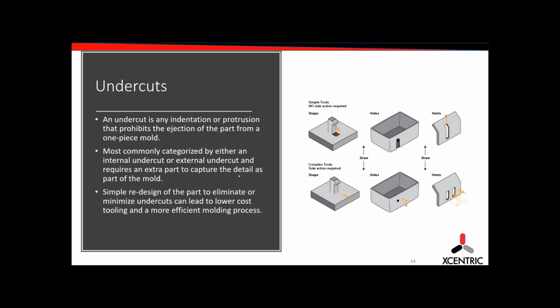It could be more, could be less, according to your part geometry. But the deeper the part, the more draft you're going to need. Especially if it's on the A surface or cavity side, and you have a texture on it. You want to be able to take that part out without damaging the surface that you are trying to achieve.